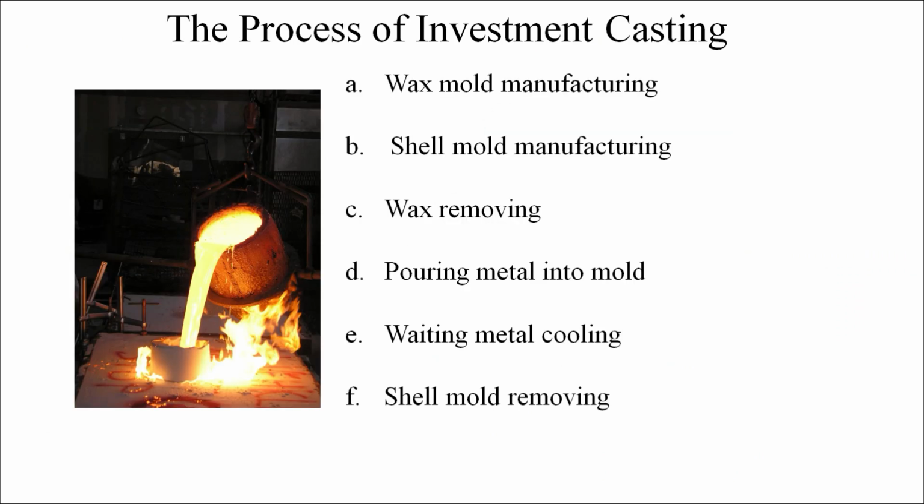Investment casting is the process of making wax molds, which are then melted and filled with metal to create metal parts. A wax mold of the same shape as the final metal part is created, which is then painted or impregnated in multiple layers to form a solid shell. The wax mold is heated so that the wax in it melts and flows out, resulting in a shell with